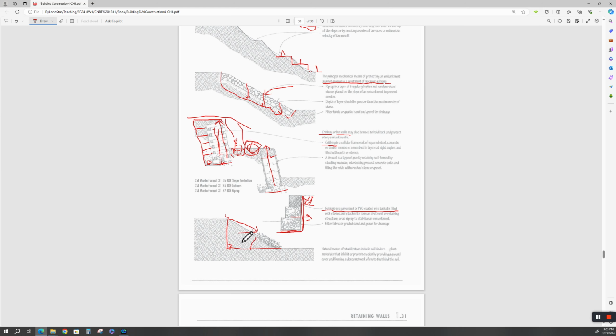So, again, yes, vegetation can be used, just like hydromulching. Texas Highway Department uses hydromulching as a stopgap on the first end. Hydromulching, in my opinion, is a waste of money for getting vegetation to start on erosion control, but that's my opinion.